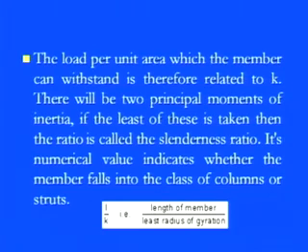Based on the value of the slenderness ratio, we can easily figure out whether the member falls in the column or the strut part. So this was the prime theory of what exactly the column and the strut are. And when we described the column and strut, we found that buckling is the key phenomenon, so we discussed the basic reasons for buckling.